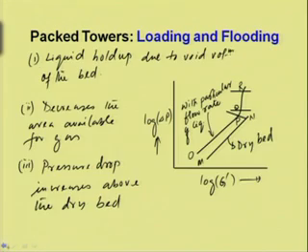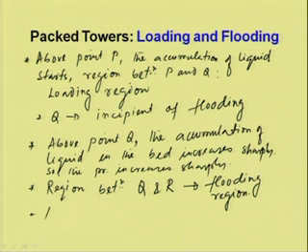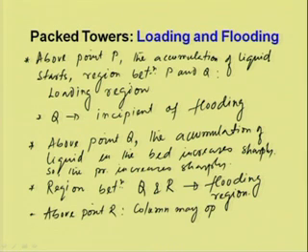As we can see, above point R, the column is completely flooded, and at that time the column may operate as a bubble column.